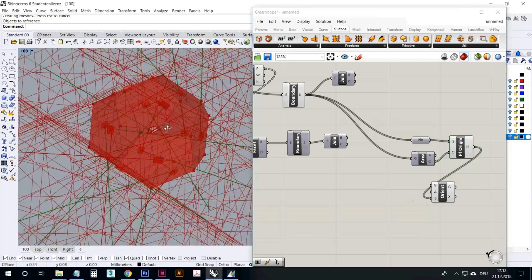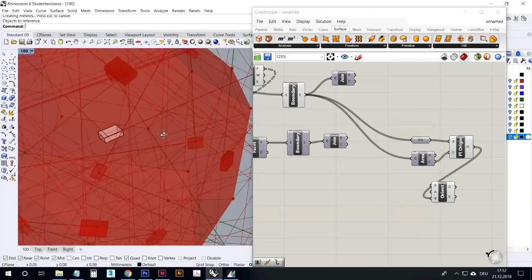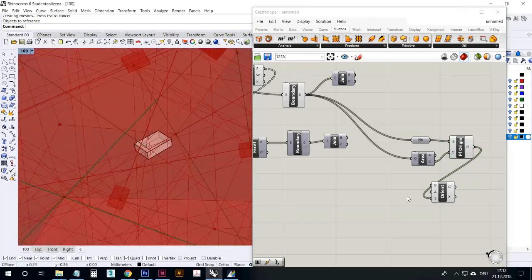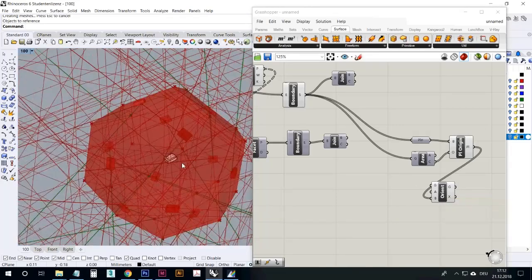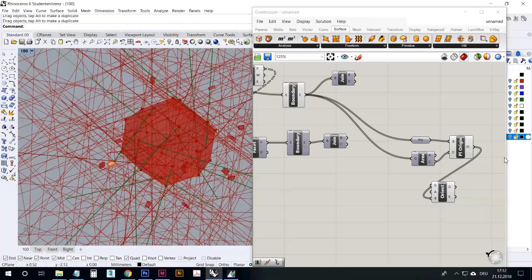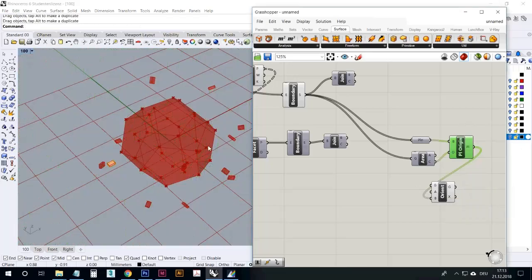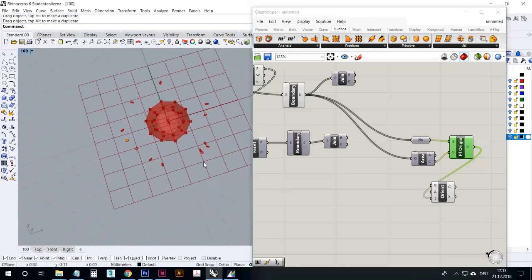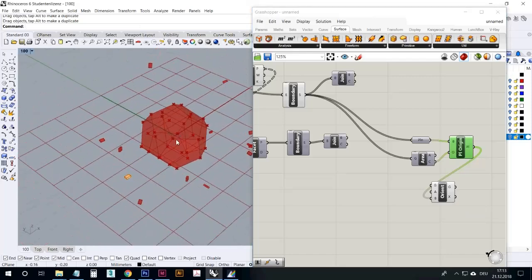So anything I draw here will be transferred to the surface. And why here? It's because the initial plane is world XY, which means that we are using anything that is in 0,0,0. So if I were to move this away, they will move away as well and leave the shape completely. It mimics anything that happens on this XY plane in relation to 0,0,0.